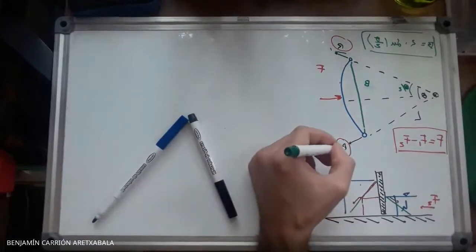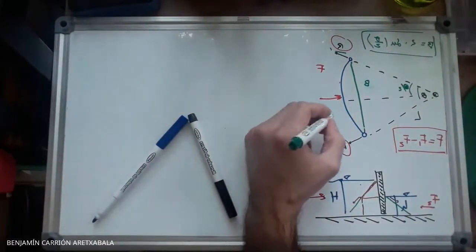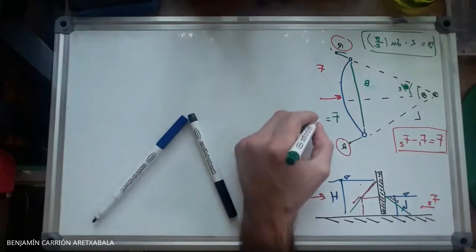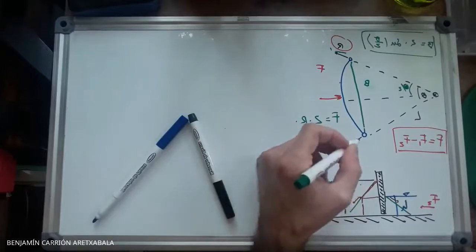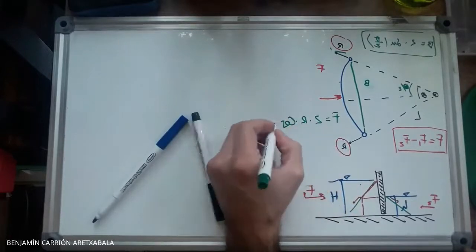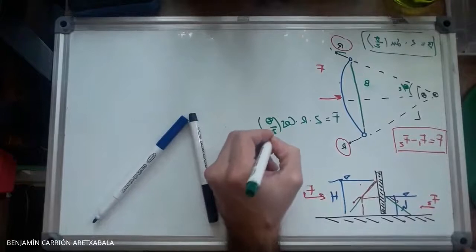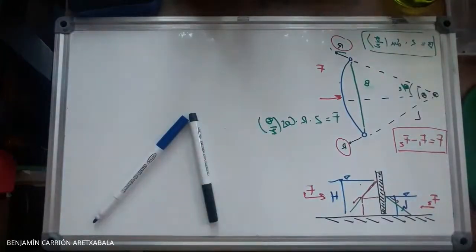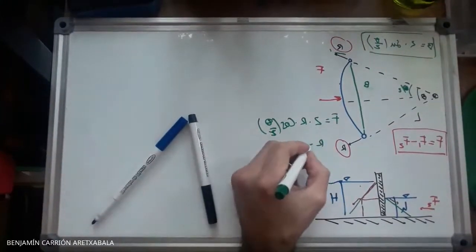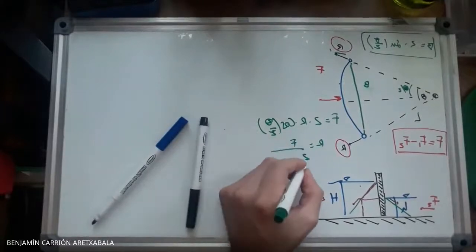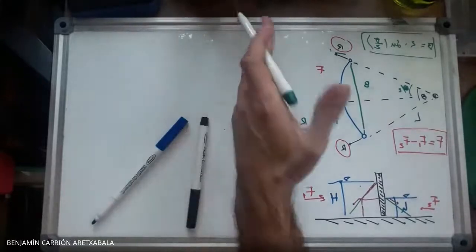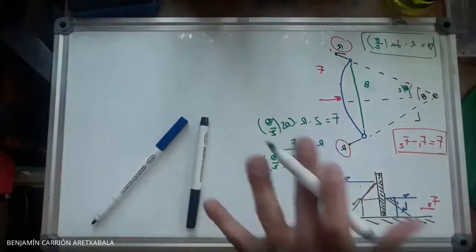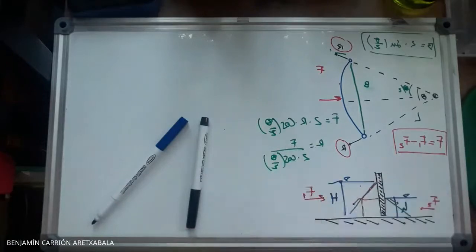So if you decompose R here, you're going to have directly that F has to be equal to 2 times R cosine of theta half, right? And therefore, R is F divided by 2 cosine theta half. Okay, so you could do this without knowing anything about fluid statics or fluid dynamics, right?